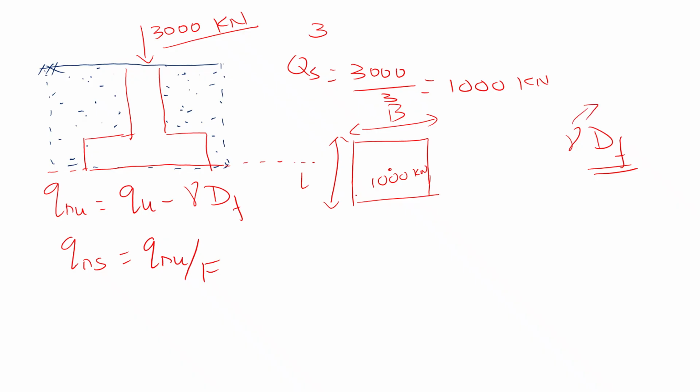Do you think I can apply a factor of safety to the unit weight of the soil because I have excavated some soil and I am refilling it inside? In case I am refilling it with an entirely different soil, the unit weight will change slightly, maybe by 0.5 to 1 kilonewton per meter cube. The unit weight may change, but yes, the effect of 3 times the factor of safety, right?